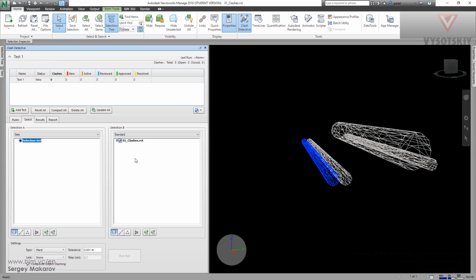And now let's find out what the buttons are. And first this one, geometry, the surface for geometry. If we want our triangle surfaces to be checked, we always need it, so we have to click it. Then this one, lines, for central lines of pipes. And if you want to check the intersection of central lines only, maybe you need it, you can do like this one.